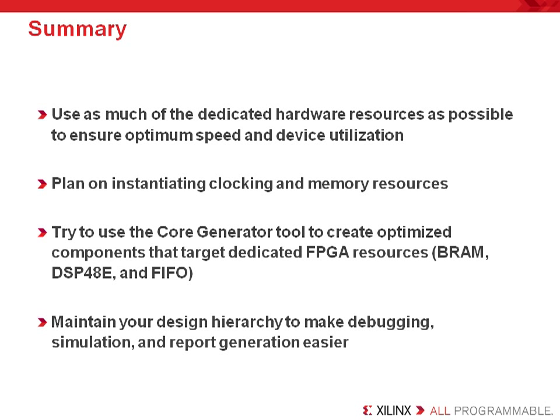Now, let's wrap up this module with a summary. First of all, use as much of the dedicated hardware resources as possible to ensure optimum speed and device utilization. And what we're talking about here is try to target as much of the dedicated hardware so it will save you using lookup tables and registers in your standard array logic.